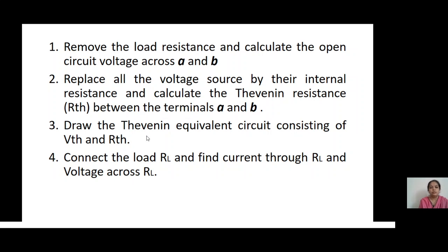The steps involved in Thevenizing a circuit are: remove the load resistance and calculate the open circuit voltage across the output terminals. Replace all the voltage sources by their internal resistance and calculate the Thevenin's resistance. Draw the Thevenin equivalent circuit. Connect back the load. Measure IL and VL.